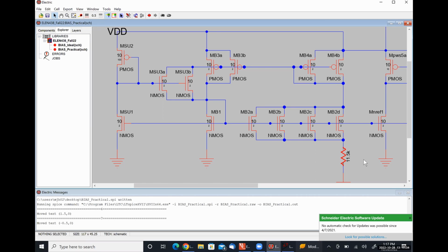So did you label it with SPICE text? No, this is, or annotation, I mean. That's an annotation. Okay, so that's why it's not doing it. You're going to be so annoyed. Yeah. Click on that. Press Control I, so label it there. So no, not annotation. You're literally giving that transistor that name. Sorry, I didn't clarify that. Yeah, it's going to take a minute. But just do that one for now and we'll see if it works correctly.